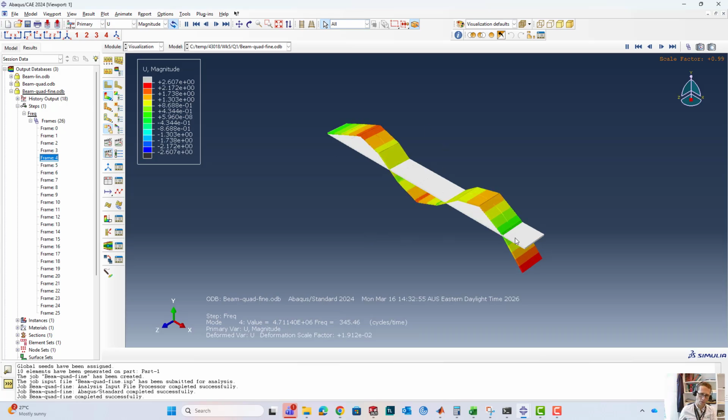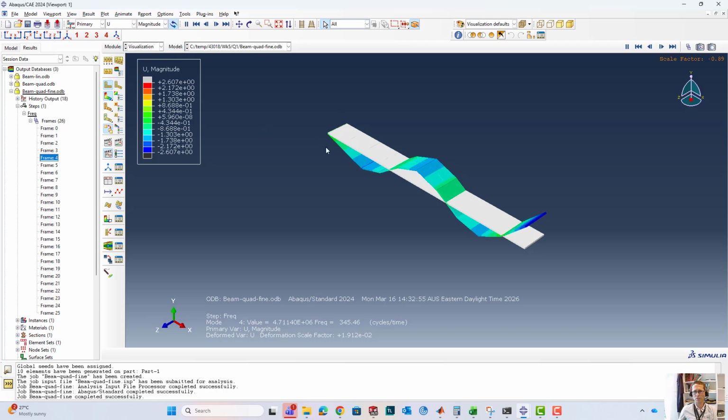Of course, we would then now instrument or build a steel cantilever beam, try to produce a fixed boundary condition at this side, instrument it with say 10 positions or 1 accelerometer on one end, and strike it in 10 locations with an impact hammer, and physically determine these resonant frequencies for such a structure. And then you can see here how you can complete this kind of a solution.